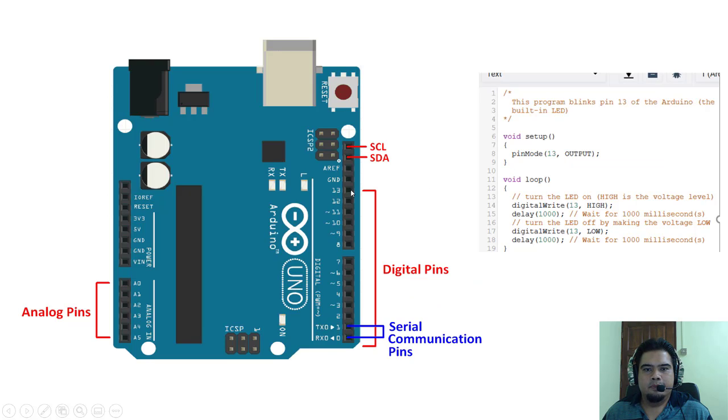So that is what happens to pin number 13. Whenever you apply digitalWrite HIGH, in circuit theory it becomes like this, 5 volt. That is what happens when you apply digitalWrite. But if you apply digitalWrite again with pin number 13 and LOW, it will become like this.